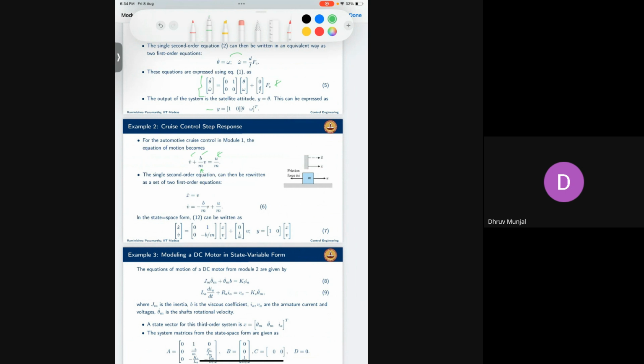When you write it in state space, you would explicitly see x here, so you can visualize the state also. From this transfer function, you can visualize how the velocity of the system would be, but not the state. In state space representation, you can visualize both the state and the velocity. So that is one good thing.